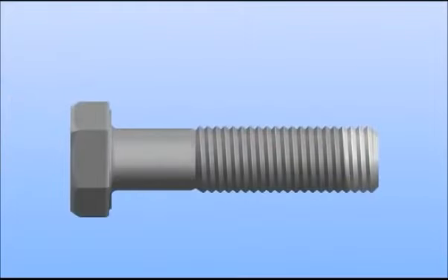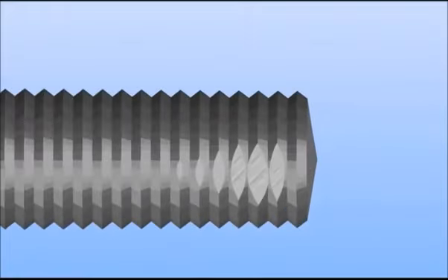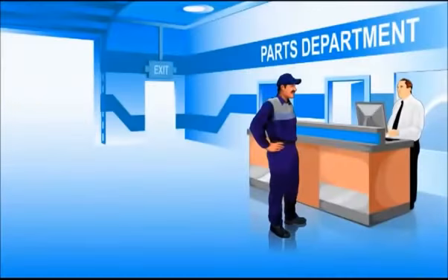If you need to clean a coated bolt, take care not to remove any of the coating, as this may result in corrosion. If this occurs, replace the fastener. If the threads are damaged, replace the fastener. Do not attempt to repair the threads. When replacing a fastener, always use the service information and/or parts catalog to make sure you use the exact fastener the component is engineered for.